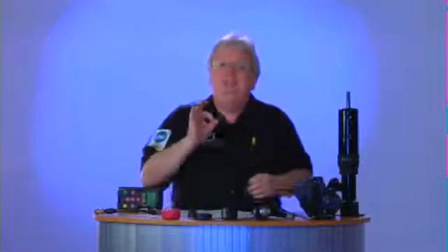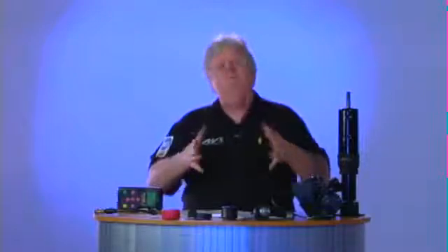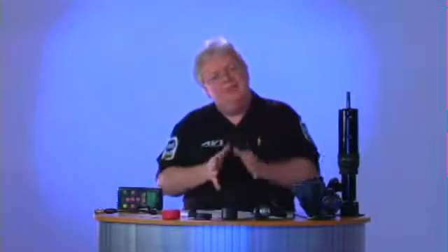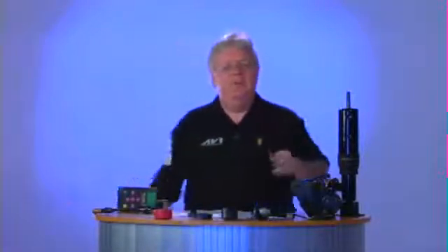Also, a defective tire, a tire with a belt that is separated, can sometimes pull to one side or the other. But definitely unequal tire inflation, one of the most basic things to do before you ever put the car on the lift and start inspecting tie rods and things. Just get out the tire pressure gauge, see what the pressures are in all 4 tires. If you live in California, that's the law. You've got to do that on every car you work on for whatever reason. You work on it and document it.